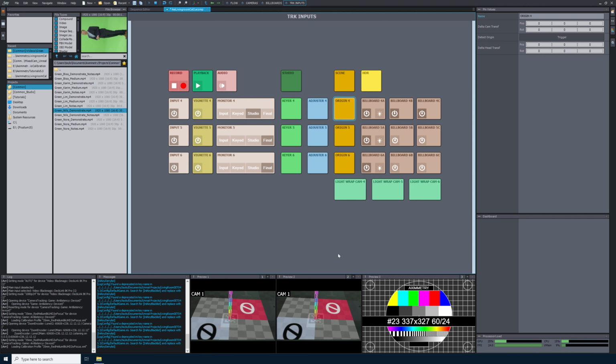I calibrated my tracking during the calibration process, so my origin is already at the center of my tracking volume. You can see where the 0,0 point of my origin is located by this virtual marker. When we trigger the Detect Origin function, it will place our origin at the center of the Aruco marker. I will select this trigger function in the settings on the right. You should see that my studio snaps into place based on the placement of this Aruco marker.